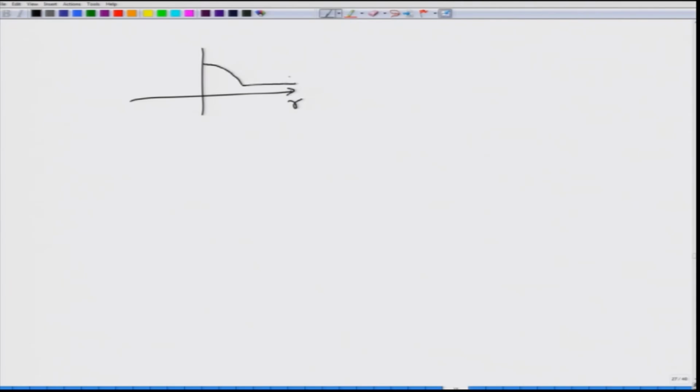In this graded index fiber, the refractive index of the cladding remains constant at N2, whereas at the center of the core the refractive index is N1, but the N1 to N2 transition does not happen like a step; it actually happens more like a graded profile. How is this bending? This bending curve is characterized by the profile parameter called alpha.